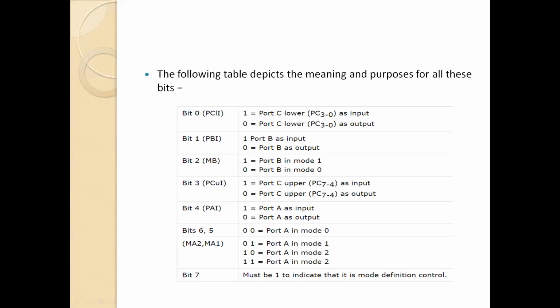When bit 1 is set, port B is performing the input function. When it is 0, reset, then port B is performing the output function. When bit 2 is 1, port B is in mode 1, and when it is 0, port B is in mode 0.